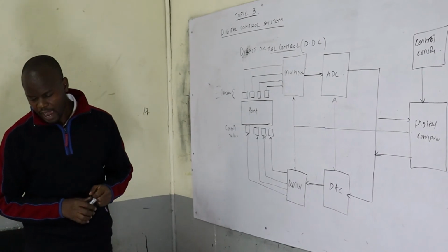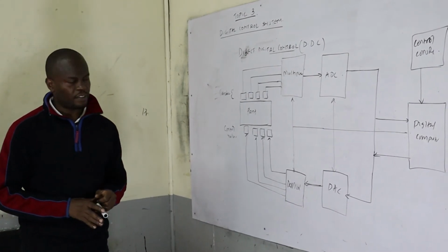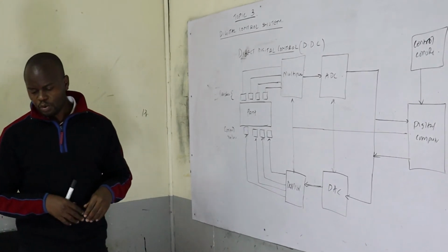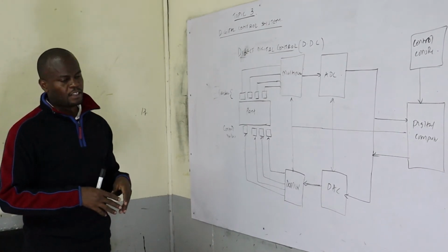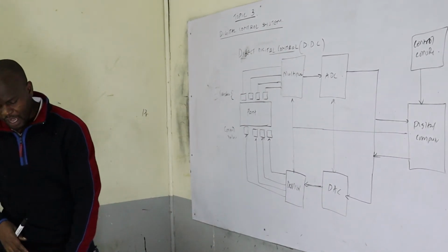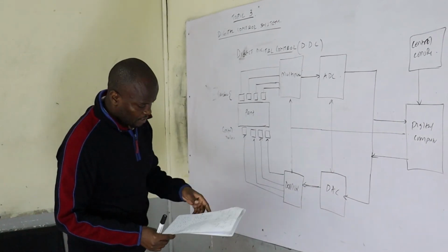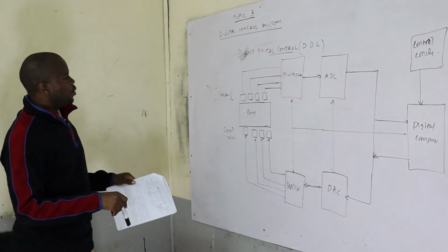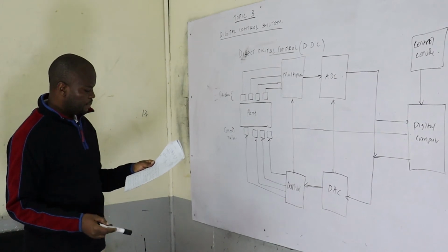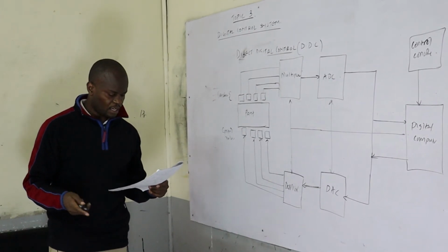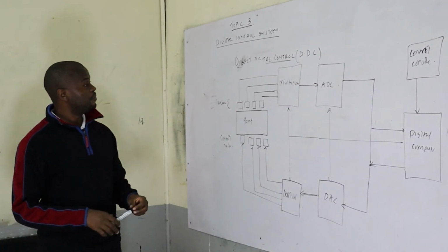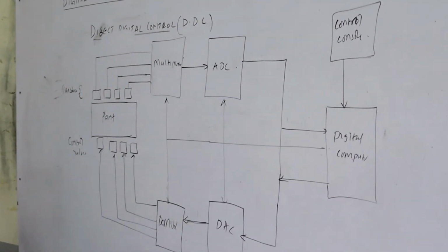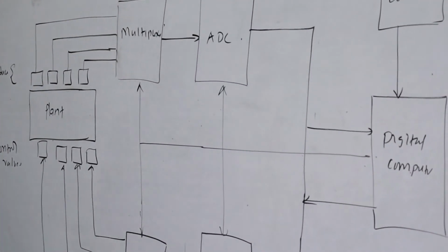It will compare with the appropriate set points on the computer program. Then it will send signals along the data bus to the valves controlling the system. And when this happens, the digital signal produced by the CPU is then converted into analog signal by a digital to analog converter. And then the analog signal is transmitted to the appropriate control valve via the multiplexer. And when all these are happening, the data will be displayed in the operator's monitor or the VDU, and if necessary, the various set points that are associated with the various parts of the processor can be remotely altered.